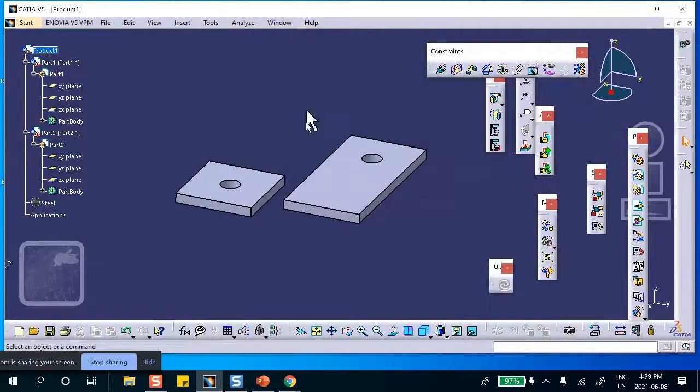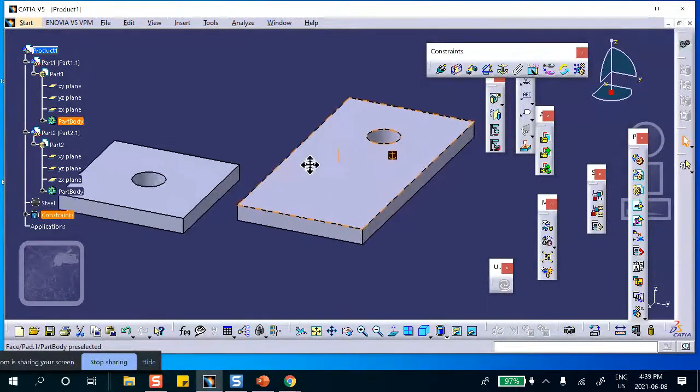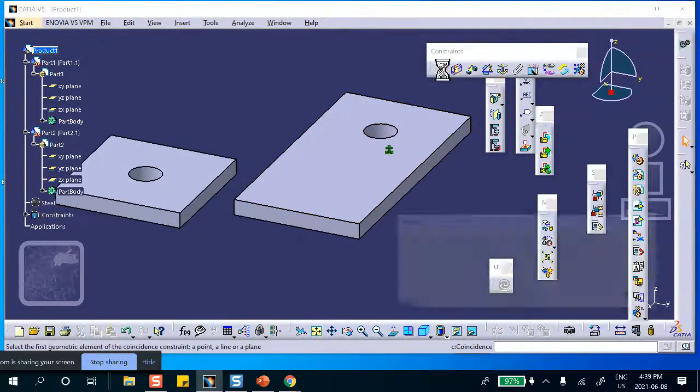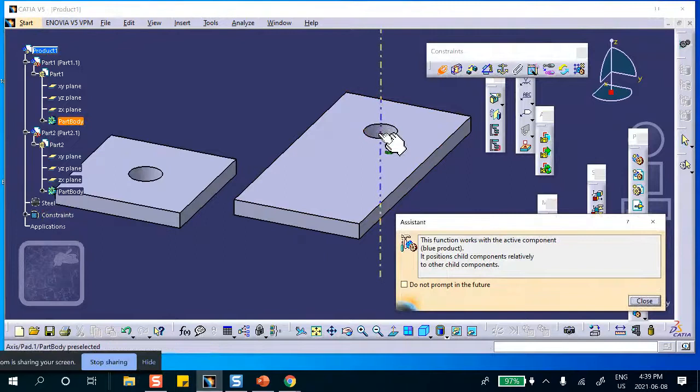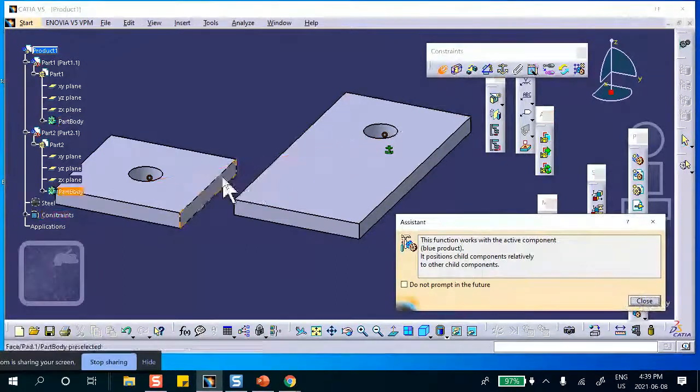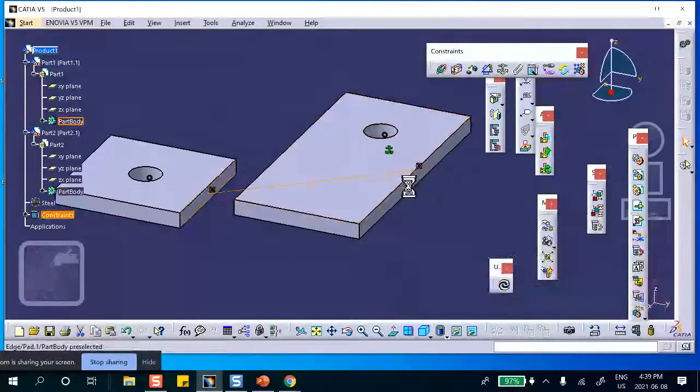let's assemble it. I didn't have to do it like this, so I could have made it right here so that it looked like it was assembled, but I'm just trying to remind you how else it can be done. Anchor something, and this anchor has nothing to do with not moving, with fixed, clamp. It has nothing to do with that. These are assembly constraints. Coincidence between this axis and that axis, and coincidence between, for example, this plane and that plane.